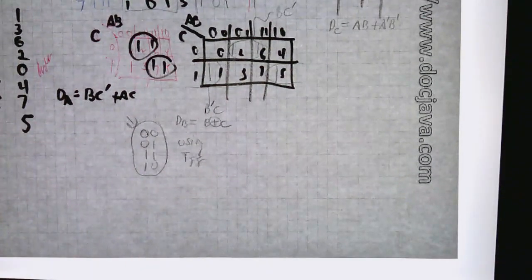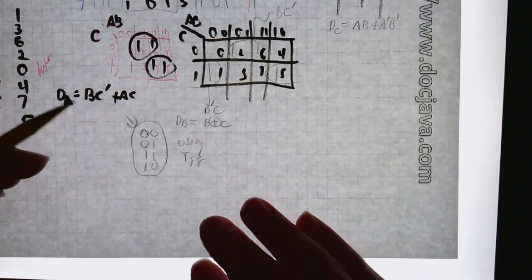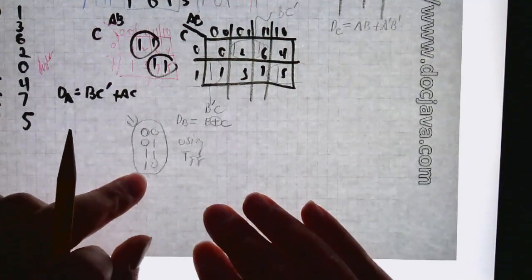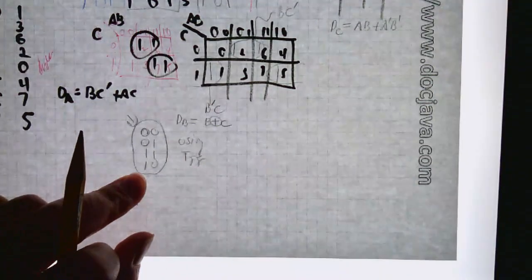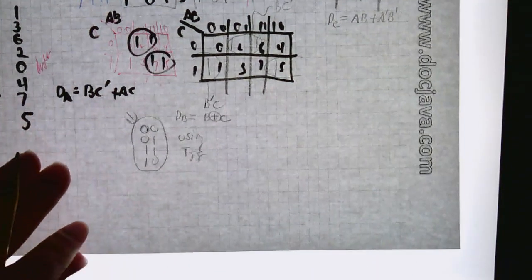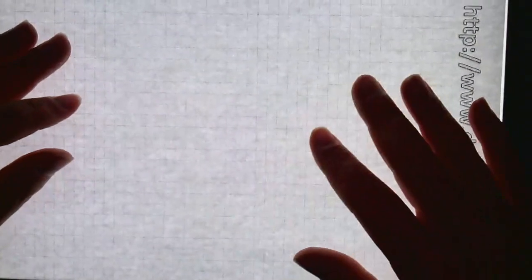Totally different question. Right? You can kind of see why that's a totally different question. First of all, it's 1 bit less. Second of all, it's using different flip-flops. So if you go through and do that, then what you get, and I'm not unhappy with the idea that we showed how to do this with 3 bits and D flip-flops, because that's a reasonable thing to want to do. Take the present state next state equation, which is going to go 00, 01, 11, 10, and then repeat, and code it in decimal,